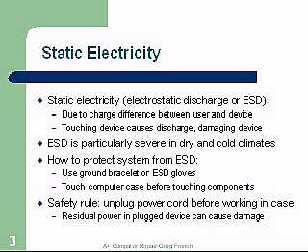How to protect a system from ESD. Need to use ground bracelets or ESD gloves. Touch a computer case before touching the components. Can't tell you how much of a problem this is. Once you take a component out of a computer, it is very subject to an ESD discharge. So if you carry it across the room, it's very likely to destroy it, unless you protect it by putting it into an anti-static bag. Safety rule: unplug your power cords before working in the case. Residual power in a plugged-in device can cause damage.